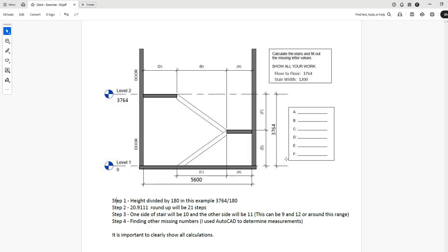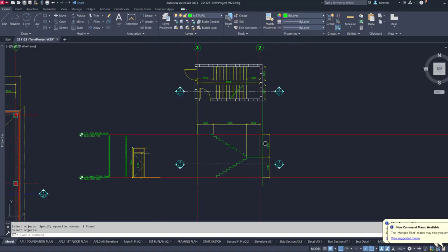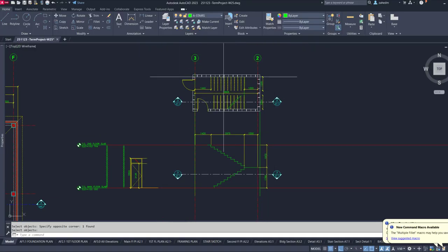But the whole point of working drawing is putting every component of a building exactly as per a specification and the physical sizes, and all those dimensions have to go together based on the construction system, materials and methods, and then all these numbers come from the real size of the material. So this staircase is constructible because everything is based on the standards.